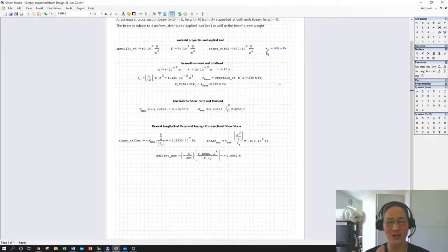So when we want to change or evaluate the impact of any one variable change, a dimension, a material property, we know what magnitude of impact it's likely to have and whether it's going to be causing which things to go up or down. In a lot of cases, we have things that unfortunately become limiting. Eventually, we're simply not going to be able to make that beam cross-section bigger and bigger and bigger for a given beam material density, because eventually the dead load will make the applied load insignificant.